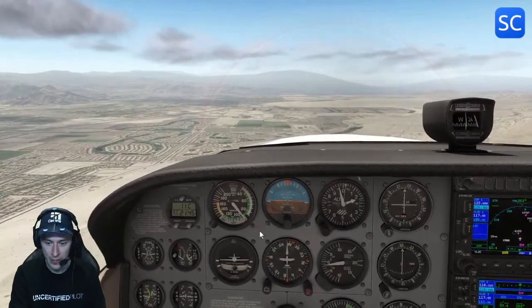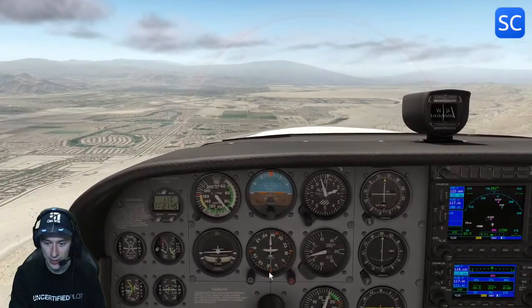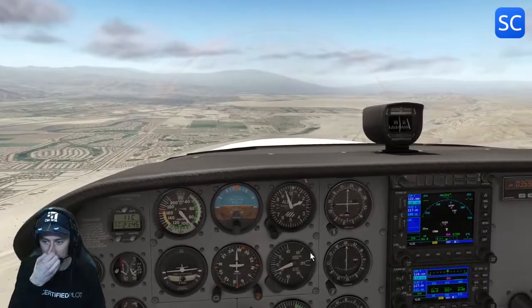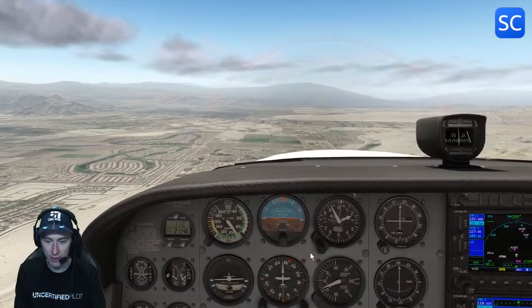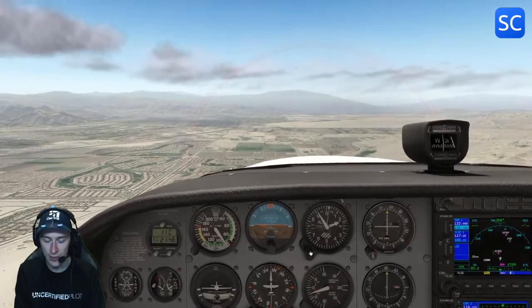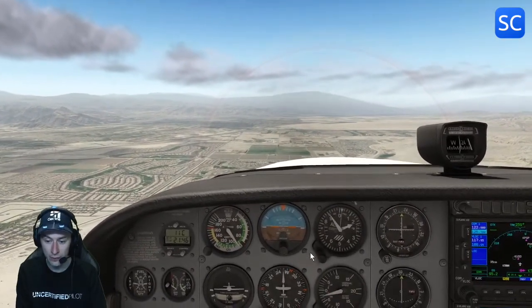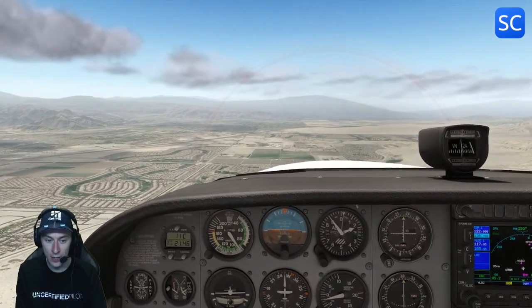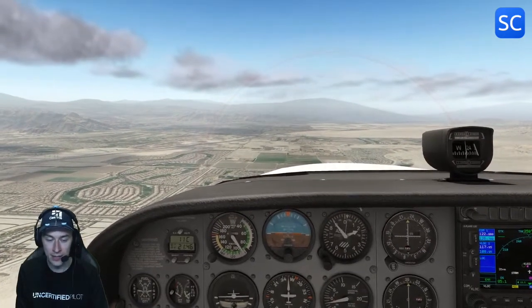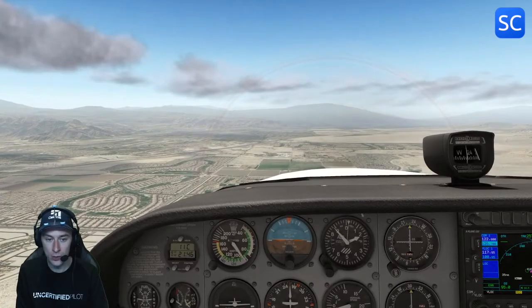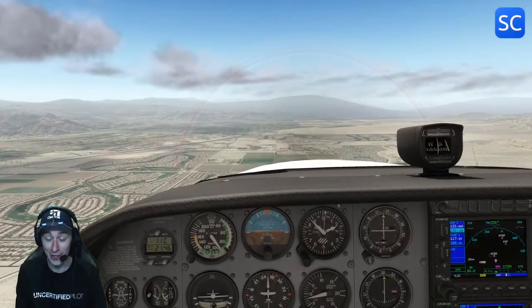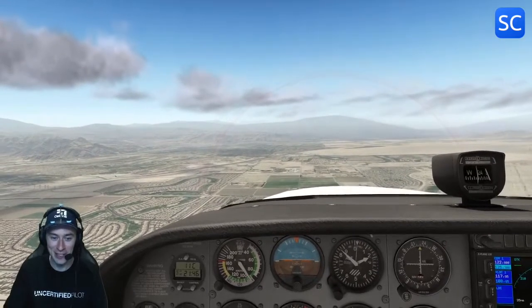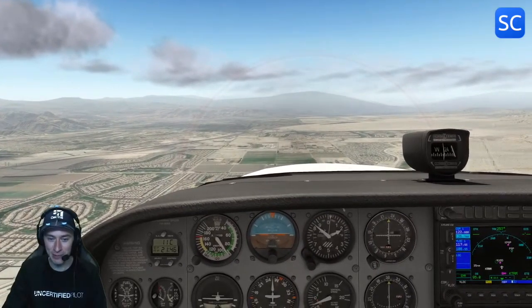Right, airport is over there, so we're currently northeast of the airport, so let's do a position report right now. Bermuda Dunes traffic, Skyhawk Papa Hotel Tango India Mike is about 3 miles northeast of the airport, currently at 2,000. We're going to overfly the field from the northeast to the southwest and enter the left downwind for runway 28 for a full stop with the teardrop. Bermuda Dunes. A lot of information there. I don't know if the teardrop addition was that relevant, but